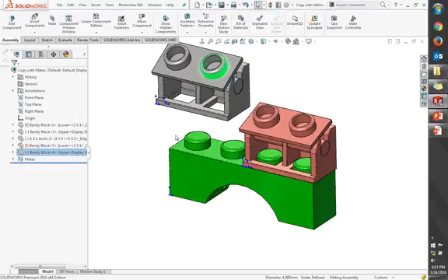Previously, if you're in anything other than 2016, probably the easiest way to do this is you take the parts, you make them a virtual subassembly, you copy the virtual subassembly, you right-click and dissolve the virtual sub. There were a lot of steps, but you know what? That was the easiest way to do something like this. So they made it that much easier, and it's not just 2 parts, it could be as many parts as you need at that time.